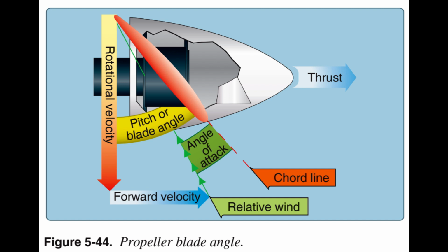For any single revolution of the propeller, the amount of air handled depends on the blade angle, which determines how big a bite of air the propeller takes. Thus, the blade angle is an excellent means of adjusting the load on the propeller to control the engine RPM. The blade angle is also an excellent method of adjusting the AOA of the propeller. On constant-speed propellers, the blade angle must be adjusted to provide the most efficient AOA at all engine and aircraft speeds.